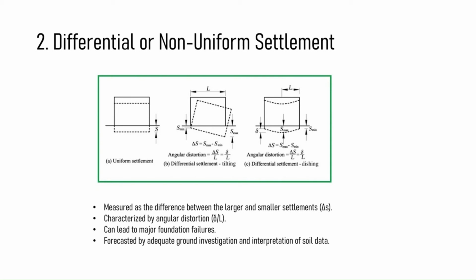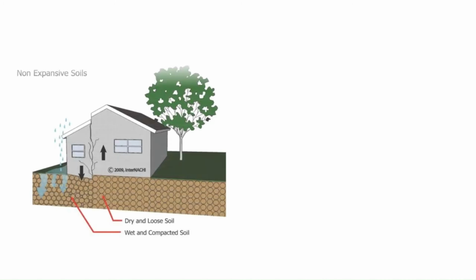Now to summarize, let's combine the various causes of foundation settlement. Foundation settlement can be caused due to many direct as well as indirect reasons, as we outlined before. Uniform foundation settlement is less detrimental. Differential settlement is a very big concern. Every differential foundation settlement issue hence has an underlying root cause that needs to be studied by a foundation repair contractor or a structural engineer before coming up with a solution.